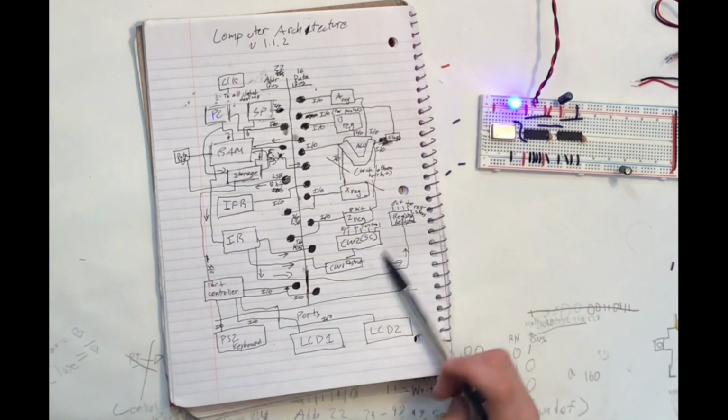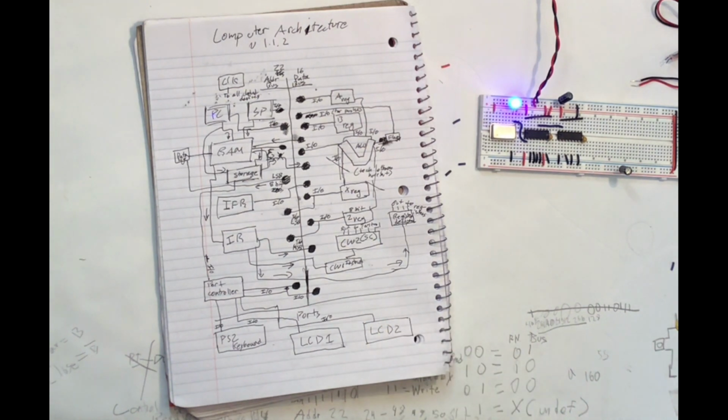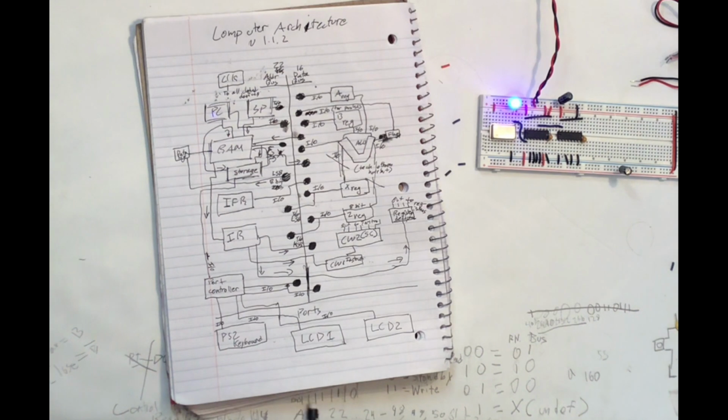So the first thing is the flags. I'm going to have the 4 flags commonly used: the overflow flag, the sign flag, the carry flag, and the zero flag. These flags will be used for all sorts of operations, jump operations, and they will be very useful in having the full instruction set very easily implemented and not having to do challenging stuff with one jump. Even though it is still Turing complete, it's still possible. It's a lot more challenging.